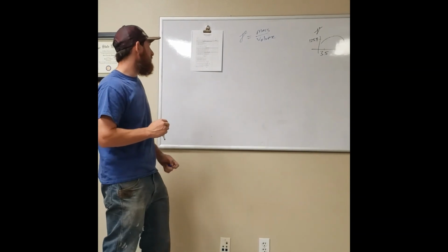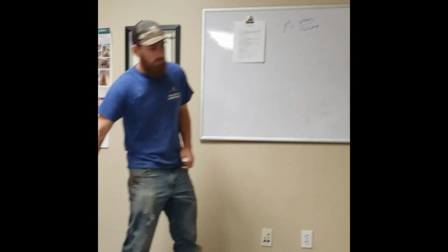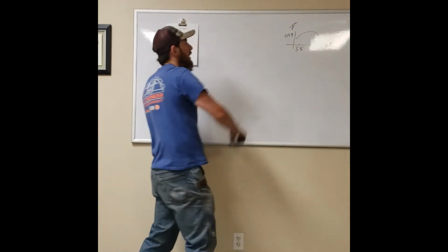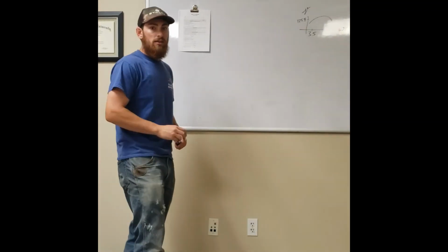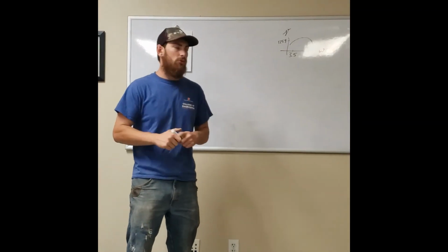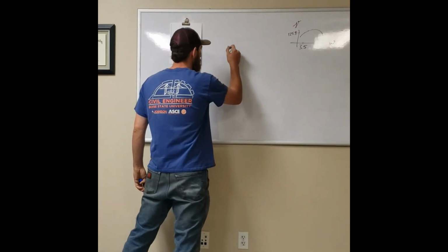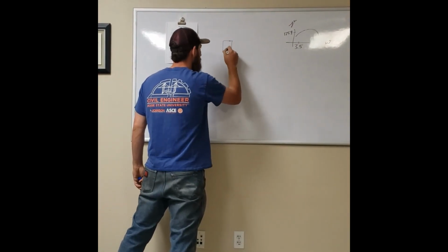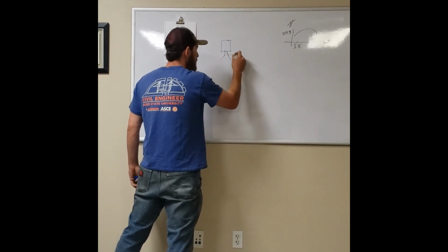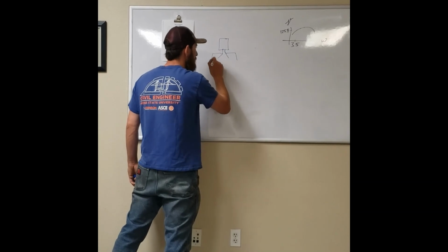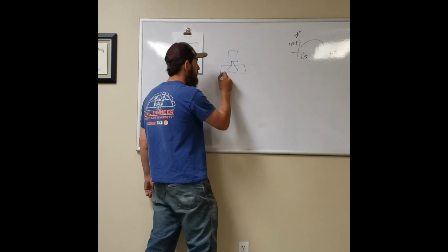Now the last piece that we're going to do is the actual field test. So again, I'm going to fill the sand cone back up. I'm going to go out into the field, into the back stretch of a lot, and I'm going to dig a small hole. This hole, because the sand's going to come in, right? So I have my sand cone on top. It's going to be my big jug, little neck, and then cone. It's going to be on a big plate. Now underneath this plate, I've got to dig a hole.